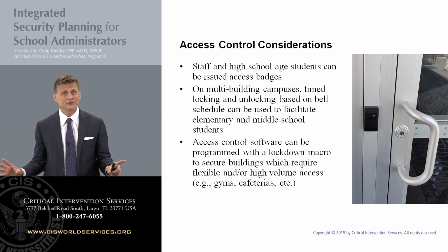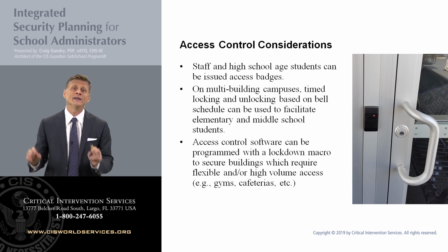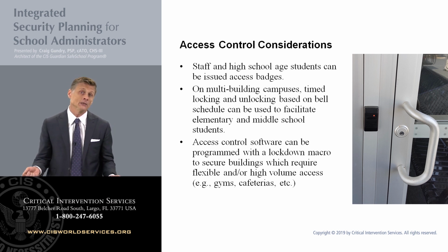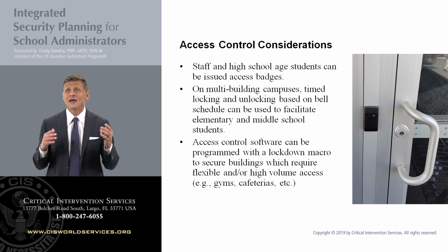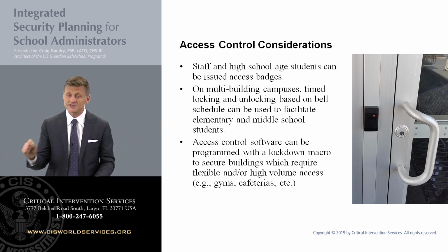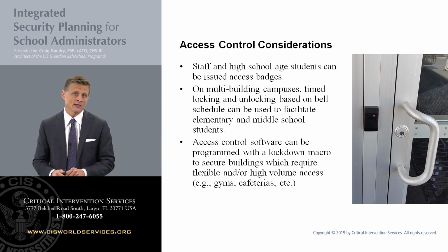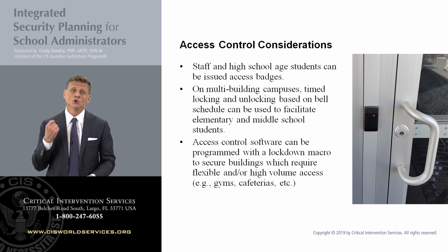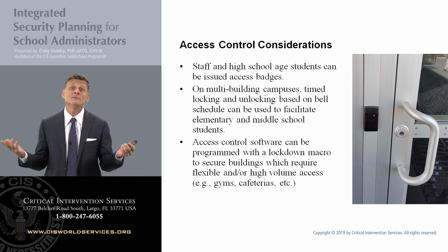Quite often in these kinds of buildings I'm describing, gymnasiums particularly, and also in cafeterias, we often find exit bar devices used on steel doors. Often we have double steel doors with exit bar devices. These require a hex key, if they're mechanical exit bars, to be locked. And it is hugely impractical to expect cafeteria staff or the coach inside of the gymnasium to run around to these different doors with a hex key and effectively be able to lock these doors. By simply installing these electrified locks and then utilizing the lockdown macro event, we can ensure that these doors get positively locked quickly when an active shooter or some other imminent threat emergency occurs.